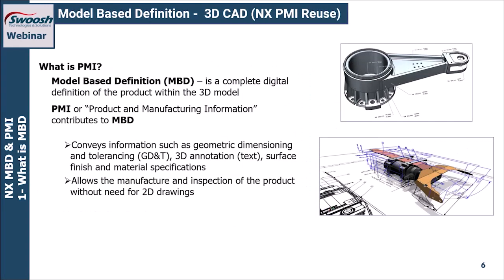So what is model-based definition? Model-based definition is the information that is going to be embedded on the model to help communicate the design of that product. So that refers to PMI in this case. PMI is part of model-based definition. The PMI is the individual dimensions, the GD&T, 3D annotation, surface finish, material specifications, all of these pieces of information that help to define the product and communicate. So this allows the manufacturer and inspection of the product downstream without the need of 2D drawings.